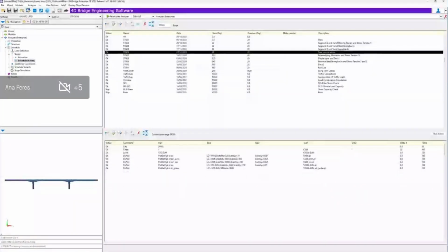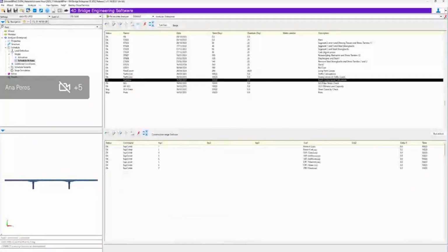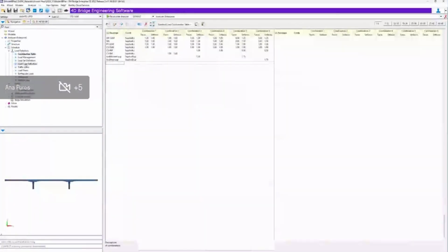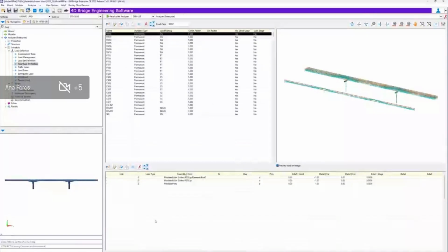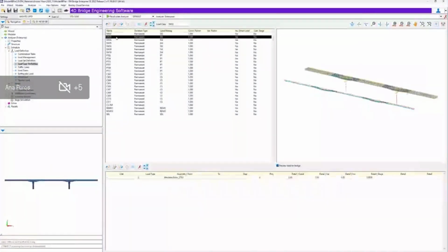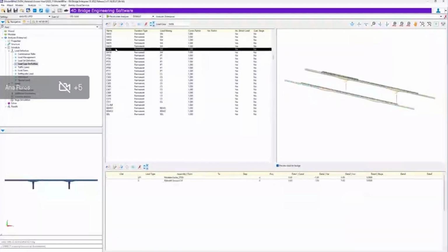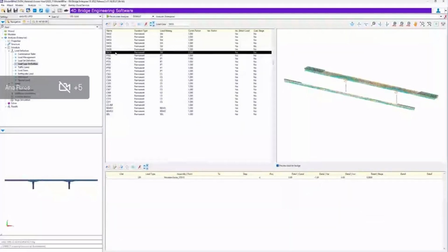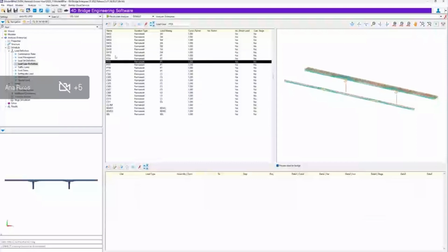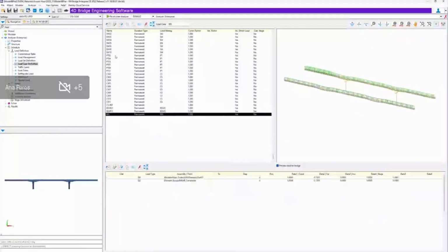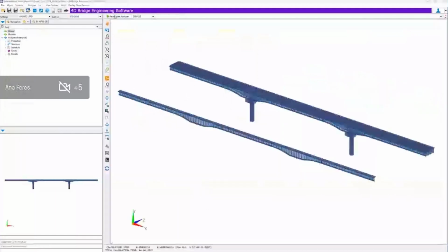So all the schedule actions are exactly the same that we presented before for one girder. The only thing that the user needs to do here is to introduce the deck elements on the load cases, in this case, for running simultaneously the 2 models, and to activate also the bridge deck elements in the stage activations.